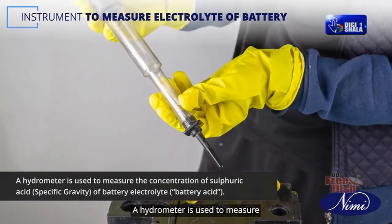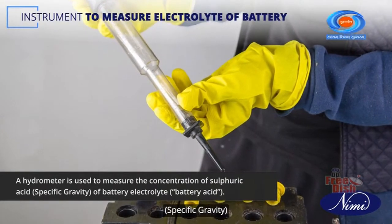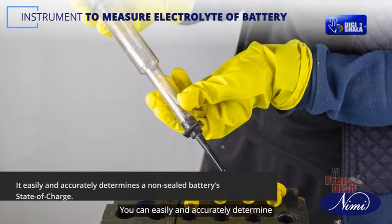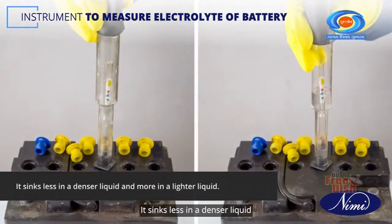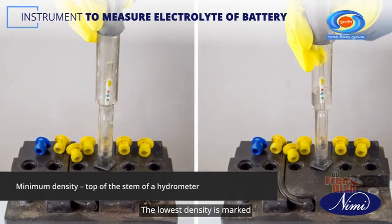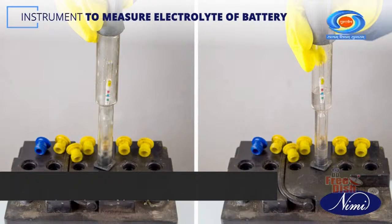A hydrometer is used to measure the concentration of sulfuric acid, the specific gravity of battery electrolyte, or battery acid. You can easily and accurately determine a non-sealed battery's state of charge. It sinks less in a denser liquid and more in a lighter liquid. The lowest density is marked on the top of the stem of a hydrometer, and the maximum density is marked at the bottom of the graduated stem.